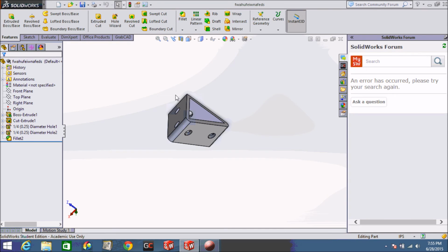Personally, the keyboard shortcuts I use: Q is for Smart Dimension, W is for line, E is for rectangle, R is for circle. So this means that when I'm working in sketches, I have all of my basic sketch functions on the QWER keys, so that I can access them without having to move my left hand basically at all.